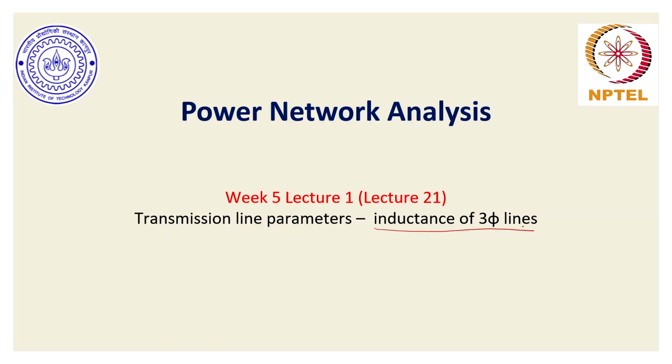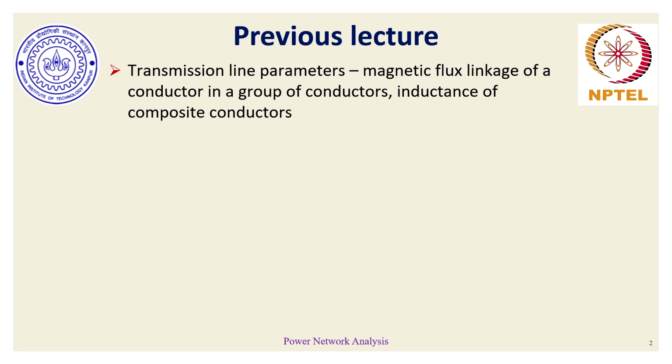And based on that, today in this discussion, we will take up our topic of inductance evaluation for actual three-phase transmission lines. And as I have mentioned, we'll take up our discussion based on the last week's last lecture discussion where we had concluded with how to evaluate inductance of composite conductors. That was still not complete, but this inductance evaluation is significantly dependent upon the magnetic flux linkages which a conductor might experience due to several groups of conductors carrying respective currents.